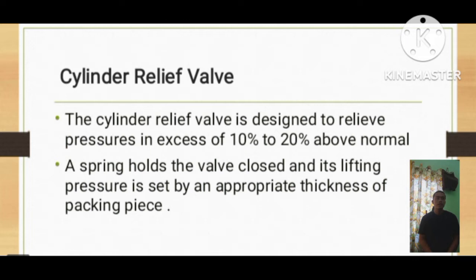So what is a cylinder relief valve? A cylinder relief valve is designed to relieve pressure in excess of 10% to 20% above normal. A spring holds the valve closed and its lifting pressure is set by an appropriate thickness of packing piece. So what to do if the cylinder head relief valve is leaking or lifted?